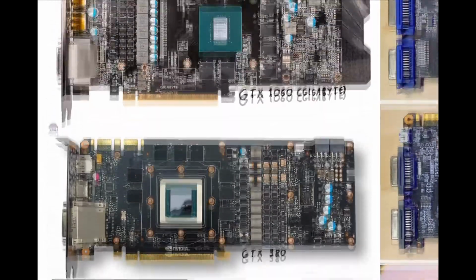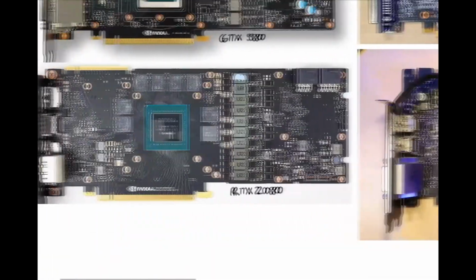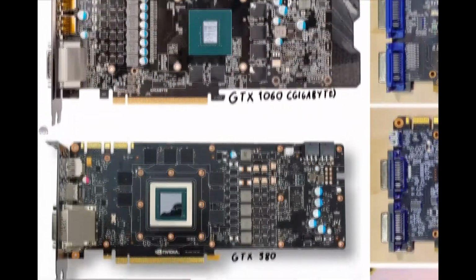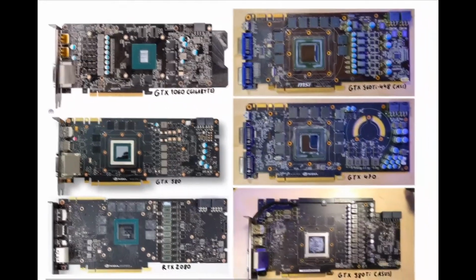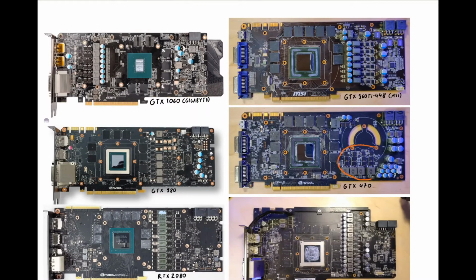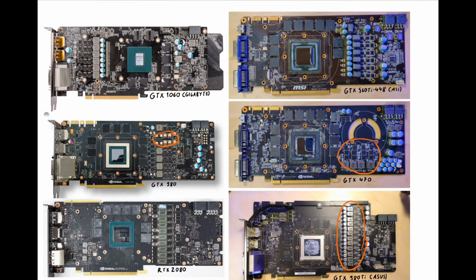So you will see that apart from the little black squares, which are the VRAM, you will also see some even smaller black squares on all those GPUs. Those are the Mosfets, and right next to them there are very often gray boxes, which are the inductors. So on our 1060 over here we have an inductor here, and then all those others are also inductors, and then we have Mosfets here. Those make up VRMs, and you can see that these are quite different from card to card. You have smaller ones, you have pretty big ones, and you can have some that have something missing in between. So VRMs are pretty different. Basically, the VRM will be the biggest difference between, say, a GTX 1080 from one brand to a GTX 1080 from another brand.